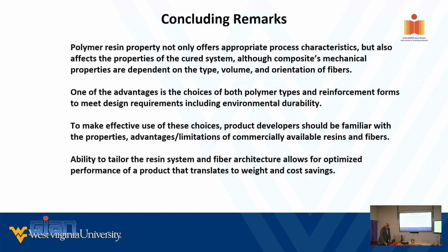Oh yeah, there are many limitations, because the thermal coefficients are widely different between glass and carbon. So you need to be very, very careful before it gets delaminated. That's why I said if it's a fairly inert environment in terms of temperature, then there should be no problem. Then why the heck you want to use a combined effect?